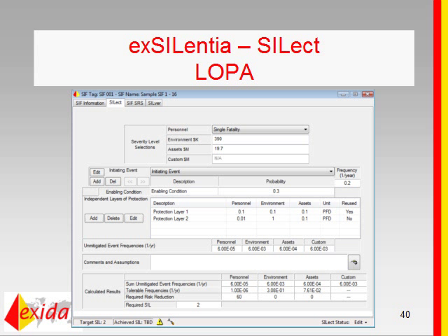Alternatively, you could have specified a SIL 1 with a minimum risk reduction factor of 60, but that goes more into the SIL selection aspects. The layers of protection are basically the same for the different selection methods. So this is how we have engineering tools that can support your layer of protection analysis methodology, and as you see, you can implement it from a pure initiating event with the different layers of cheese, so to say, perspective, or you can also put the layers of protection and embed those in your risk graph and hazard matrix analyses.